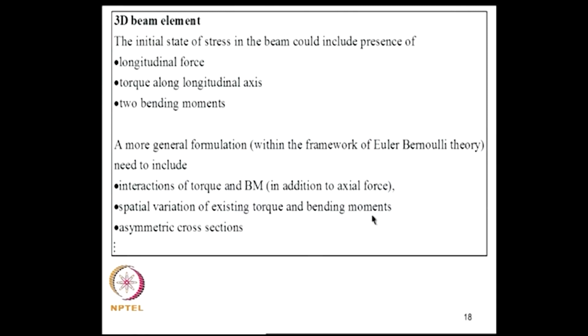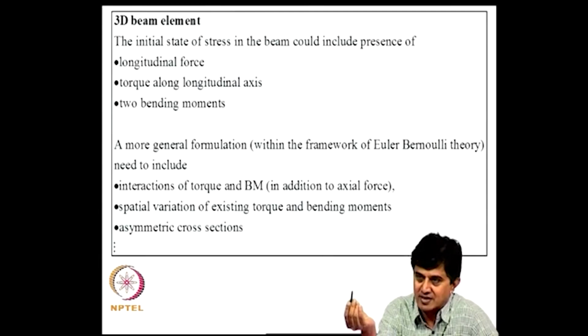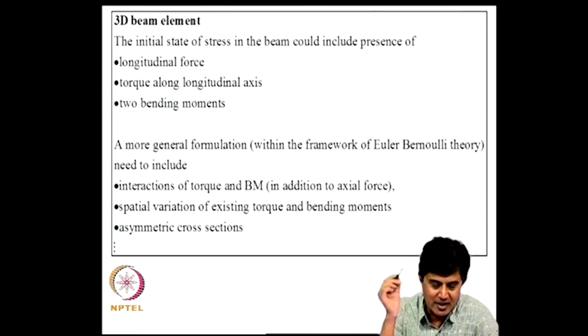Okay. So, it is reasonable to assume axial deformation is constant over an element, but bending moment and twisting moment need not be constant. Because in a pre-stress when you draw your bending moment, shear force, and axial thrust and torque diagrams, they need not be constant, they can vary within an element.